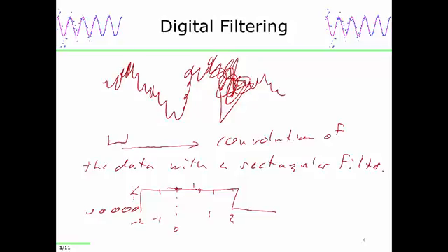Let me point out another couple interesting things. If I am convolving the data in this way with this running average, what do I do about the first and second data point and the last and second to last data points? I have a problem there, right? What is the problem with trying to apply the rectangular digital filter for the very first data point? Yeah? You don't have the 2 data points to the left and the 2 data points to the right for the average. Yeah, I can't apply it when these don't exist and when these don't exist.